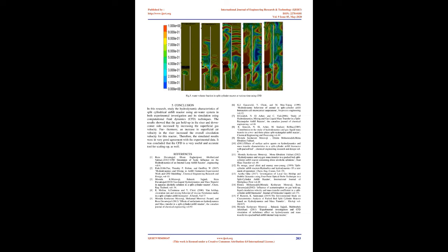Boundary conditions for the principal equations were assumed without any slip on the walls. For inlet and outlet, the boundary conditions were the velocity inlet and the pressure outlet, respectively. The liquid phase was the primary phase and the gas phase was the dispersed phase. Figure 2 shows the distribution of gas.